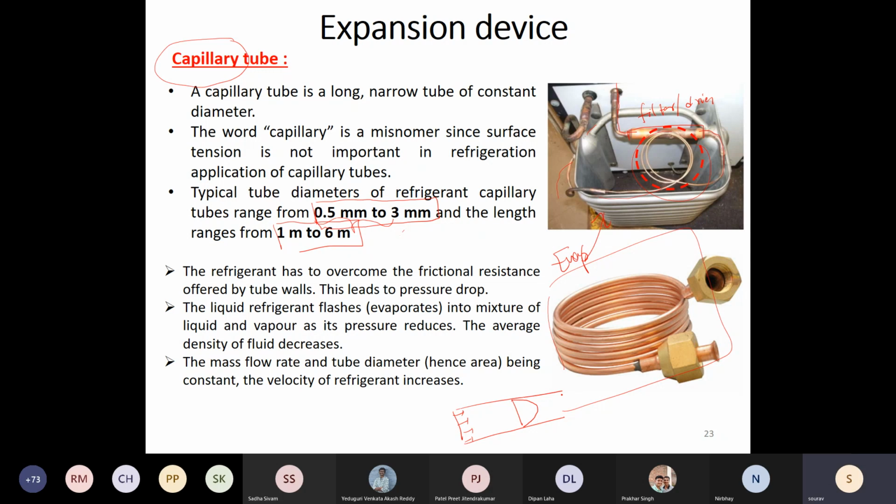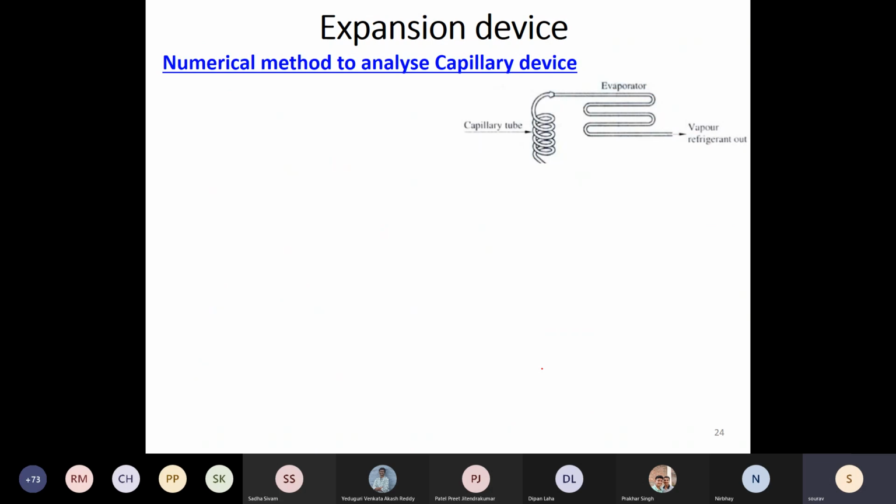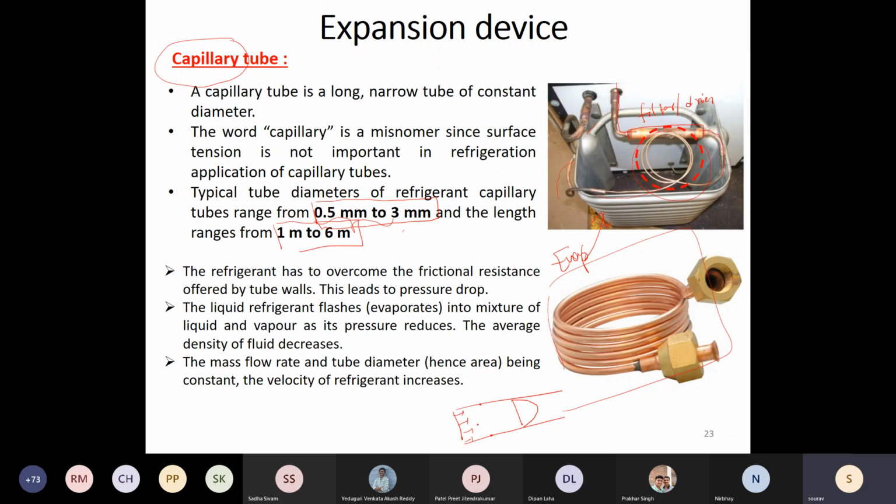So the fluid packet next to your pipe wall will come to rest. No slip boundary condition. Okay, so these circumferential edges will have zero velocity. And that will lead to an acceleration of the fluid flow near the center line.